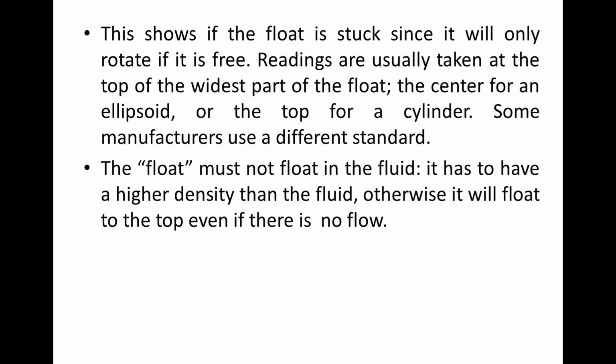Already you have seen the float is stuck since it will only rotate if it is free. Readings are usually taken at the top of the widest part of the float, the center for an ellipsoid, or the top for a cylindrical shape of the float. Some manufacturers use different standards. The float must not float in the fluid. It has to have a higher density than the fluid. Otherwise, it will float to the top even if there is no fluid.